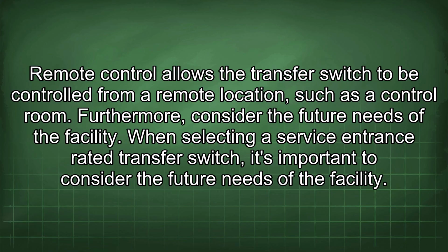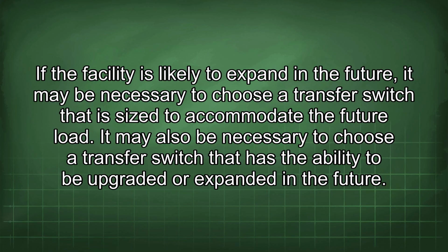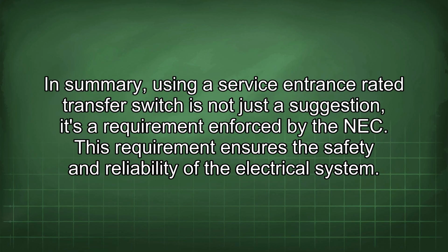Furthermore, consider the future needs of the facility. When selecting a service entrance rated transfer switch, it's important to consider the future needs of the facility. If the facility is likely to expand in the future, it may be necessary to choose a transfer switch that is sized to accommodate the future load. It may also be necessary to choose a transfer switch that has the ability to be upgraded or expanded in the future. In summary, using a service entrance rated transfer switch is not just a suggestion,